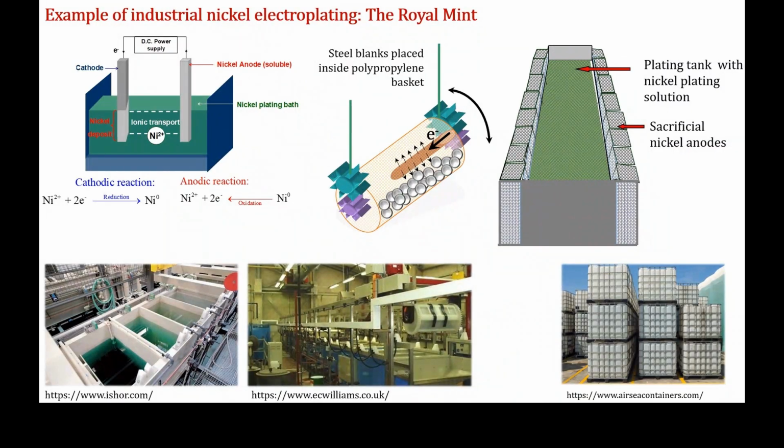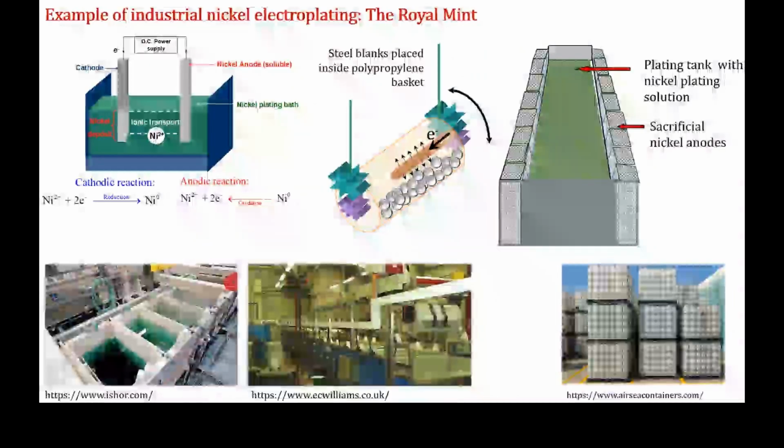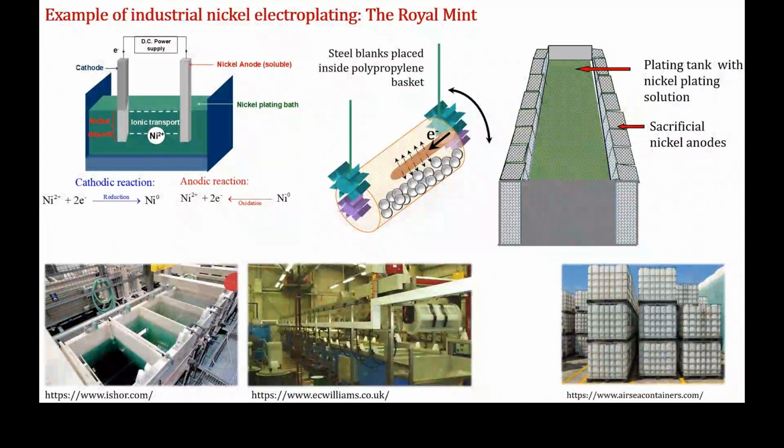You can use electrodeposition to generate a coating that could be an undercoat for another more valuable material. For example, if you're plating nickel, it could be used as an undercoat for gold, tin, rhodium, and chromium plating because it creates a better metallurgical bond with different substrates. So you would sequentially electrodeposit progressively more noble materials on top of each other until you get the finish that you want. You can co-electrodeposit different materials together to generate alloys.